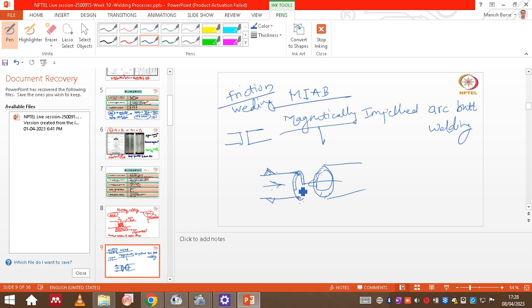And actually, because of heating, the heat affected zone or partially melted zone which is present at the interfaces, during the upsetting of the other component, this partially melted zone will be coalesced with each other by mechanical coalescence or mechanical deformation. Okay, so it is not completely a fusion welding process, but again it is categorized as fusion welding because at the start of the process we have to strike the arc, right? And the interfaces are in the molten state at the start of the process, right?